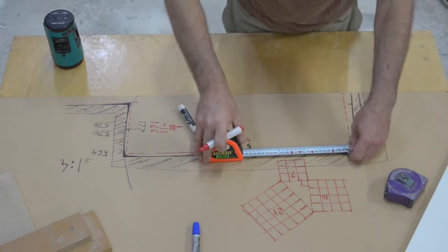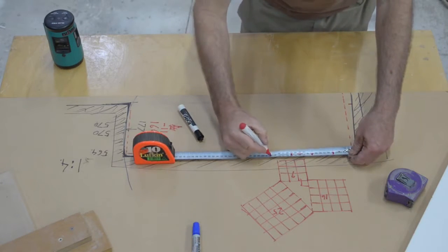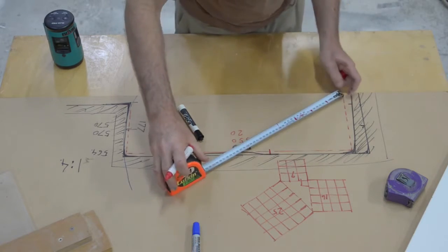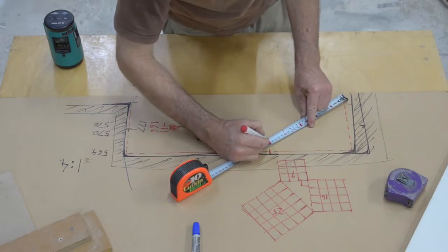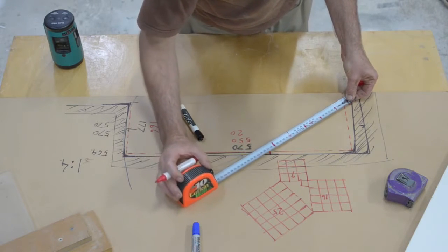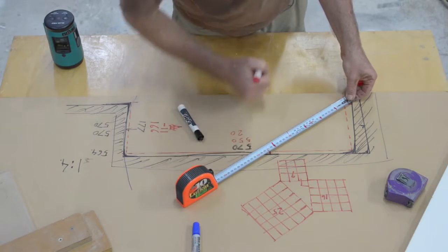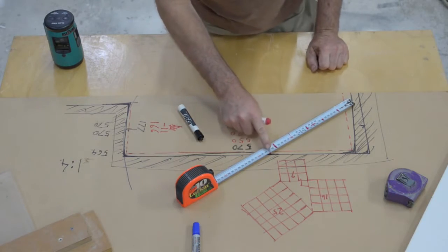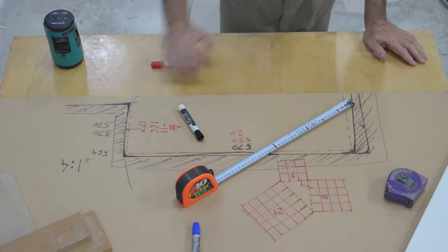And from this way, we'll do 4 lots of 50, which is 1, 2, 3, 4. Now what's our diagonal? It should be 25 centimetres or 250 millimetres, and it isn't. It's a much greater distance. It's 273 millimeters. So it should be 250, and we end up with 273.